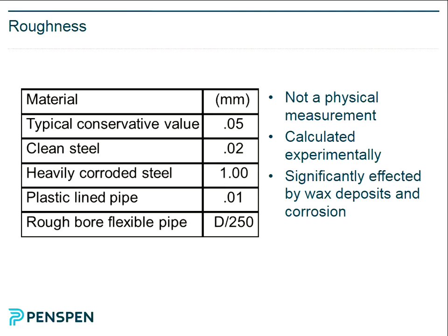Something which you typically need with multi-phase flow is a slug catcher, because you're getting gas and liquid being produced at the end of your pipeline. The question is, what do you do with them? So typically you have a big vessel which catches the liquid. The gas goes off, the liquid is caught in the big vessel, and is then produced at a slower rate. And slug catchers, because they're operating at pipeline pressure, need very, very thick steel. They end up being very expensive bits of equipment. So again, dense phase avoids the use of a slug catcher.